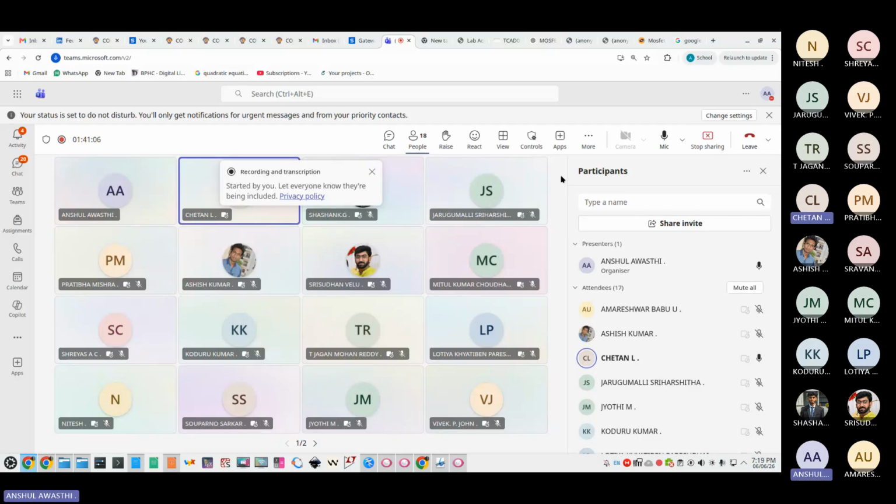First of all, the context name should be the same in both SCM and CMD files. While creating the structure, you should give the same context name as whatever there is in the CMD file. Also, the mesh file name. Whatever name you are giving to your meshing file, that mesh.tdr file name should be there in the CMD file because it will take the input of that mesh.tdr file. Yes, that's most important.